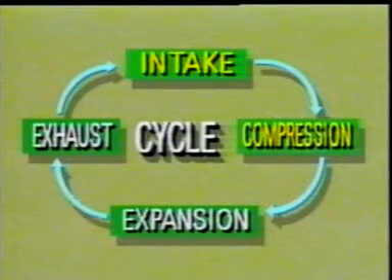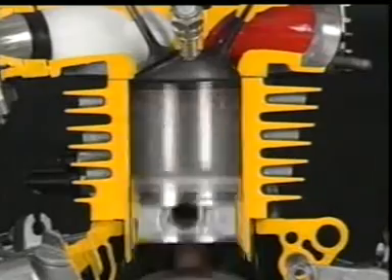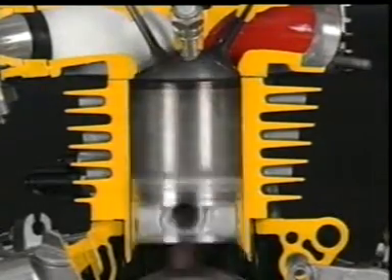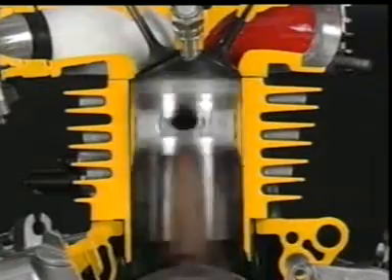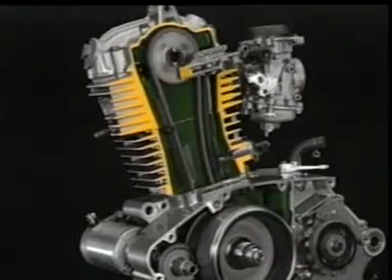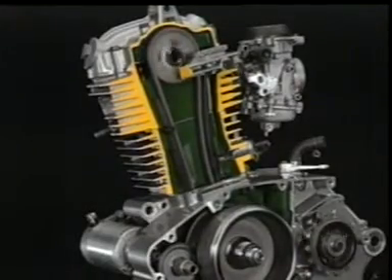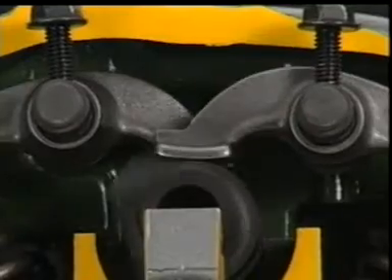Each cycle is composed of the compression of the fuel-air mixture after intake, and the conversion of the force produced by gas expansion upon combustion. Each cycle is divided into 4 stages: intake, compression, expansion, and exhaust. Engines are designed in order to complete the different stages of each cycle without interruption. Many measures are taken so that the intake and exhaust will be executed smoothly.